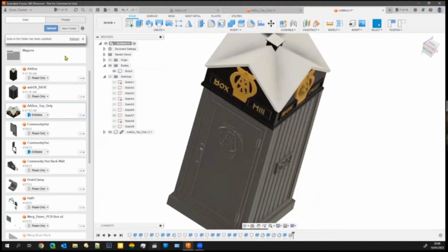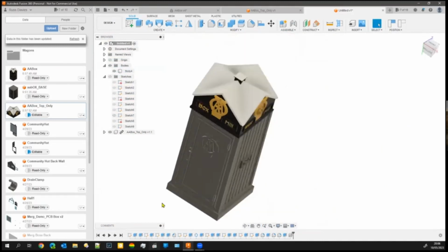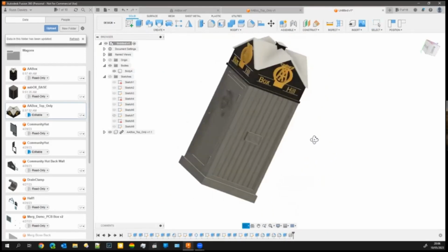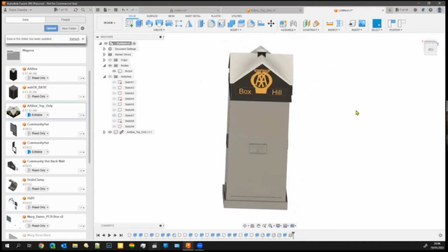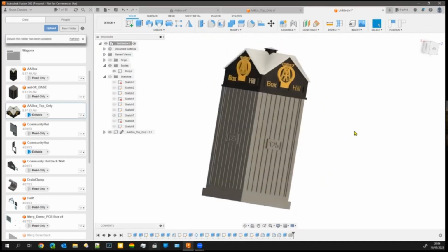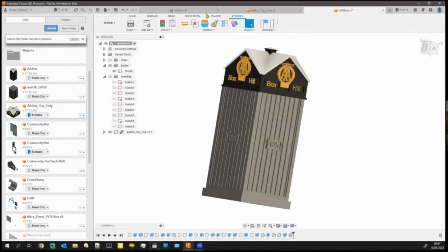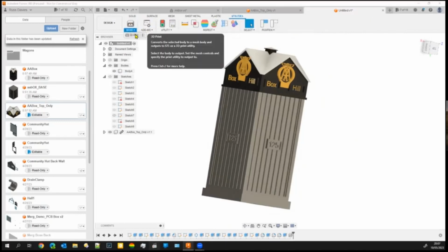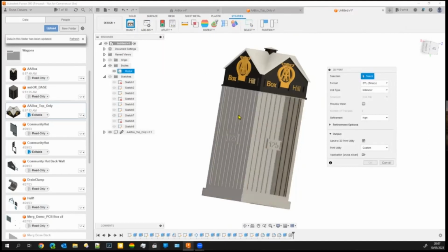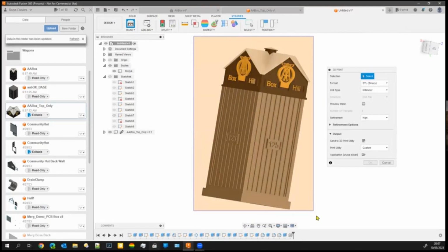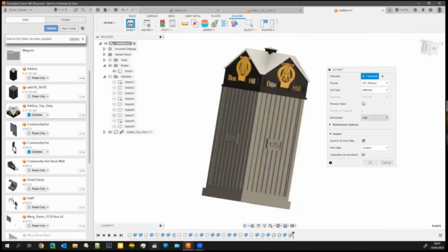That's basically it. Can you just show how you'd export the STL? So, oh yes, sorry, by all means, certainly. I will do that now. So that's the complete thing. Now, Fusion has got a slight oddity with STL, is that if I go up to utilities and do a make and a 3D print, I can only highlight one. I can't highlight both of them. And this will go straight to my slicing program.